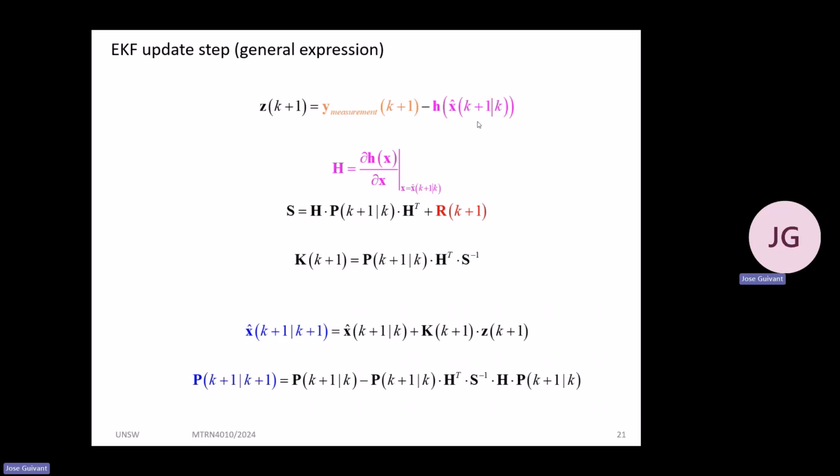And this one is also lying a bit, because it would be the hypothetical output variable if the state of the system were our expected value about the state of the system, but our expected value about the state of the system is not perfect anyway. So we get a discrepancy here. And the name of this is usually the innovation. The innovation is telling us the discrepancy between the actual measurement and the expected measurement.